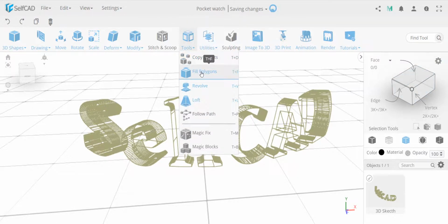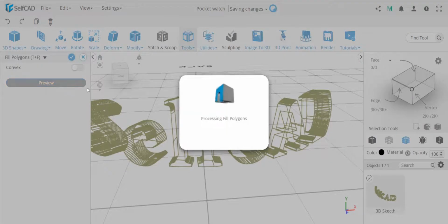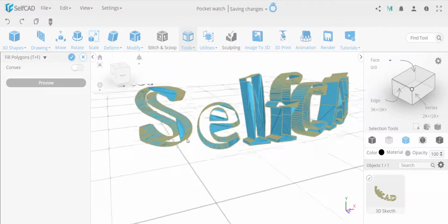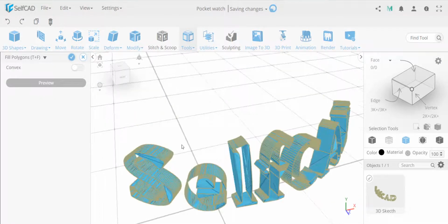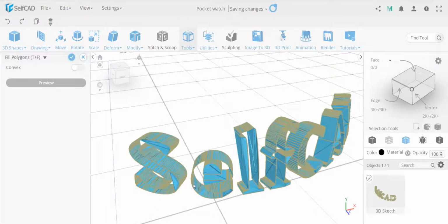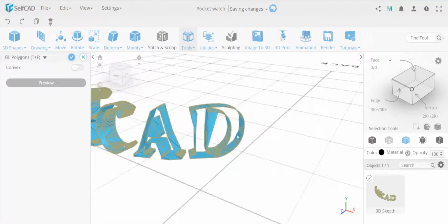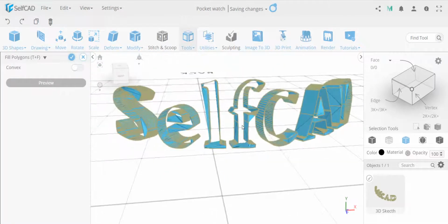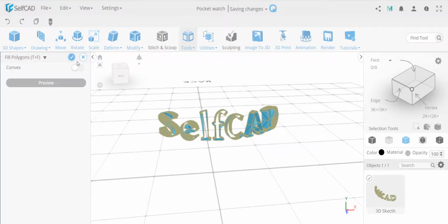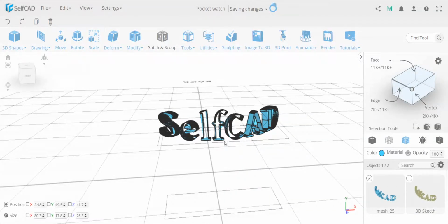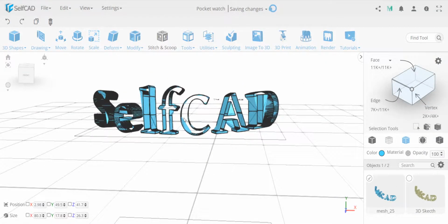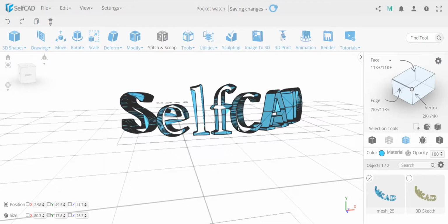If you go to Fill Polygons, which is the basic way to fill a polygon to convert a mesh, you can see it tries to fill all of these outside spaces. Partially it fills over here also, and over here, and this is obviously less than desired results. If you wanted to convert this into a mesh, you would have to finalize it, play with the mesh itself, delete pieces, and then use fill polygon again on the mesh, and this would be very difficult.